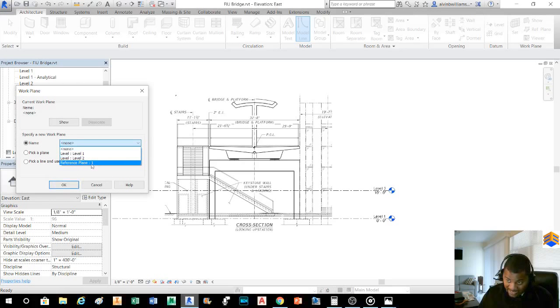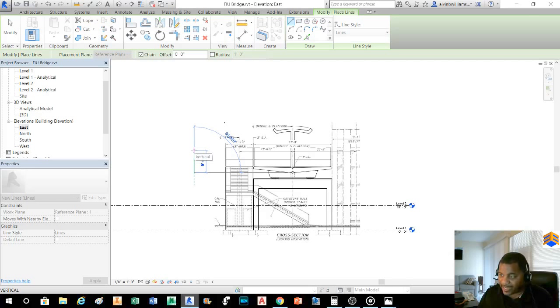Now it's basically going to draw. What I'm going to do is, and I apologize, I got ahead of you a little early before I started creating this video. But anyway, before I do anything to the picture other than import the picture into Revit, I would create a reference line at the length that I'm trying to scale the image to.